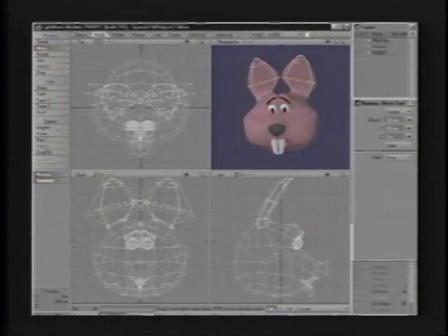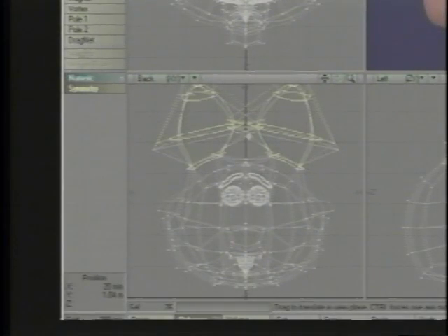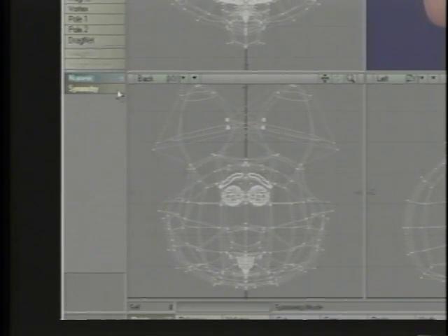Keep in mind that symmetry is acting along the y-axis here in this view. If we look closely, what we can see is that in order to make the ears stretch out like this, we had to stretch the original cage points clear over here. So this ear, to get this little bend here, has points on this side of the axis. Let me turn off my symmetry so you can see that. You see these points here affect this part of the ear. If I drag it over, you see, that's what's affecting that curve. So obviously, if I have symmetry turned on and I'm trying to move this ear, since this point is on this side of the axis, when I move this way, it's trying to do the same thing in the opposite direction that way. So what I'd have to do is actually turn off symmetry, get these points over, turn symmetry mode back on, and then pull the points back out.